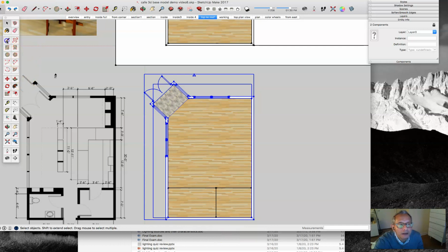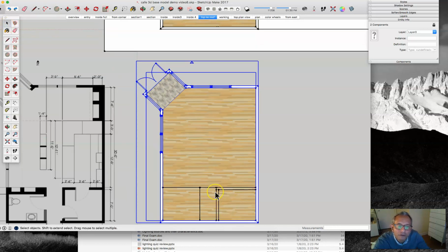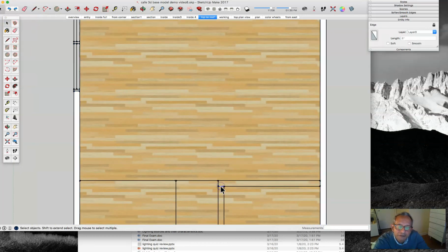Okay, so I'm going to do another line. I'm coming in, and this wall comes over 8 feet. So I'm going to start here, come across 8 feet and go down. I'll draw in this back wall here, 6 inches, so I go down 6. I'm just going to go over and run into this line over here, and it remembers the dimension, which is quite nice in SketchUp. Hopefully that's all linked up. I'll just delete that little piece in there. Yes, and now I have a surface which I can extrude.